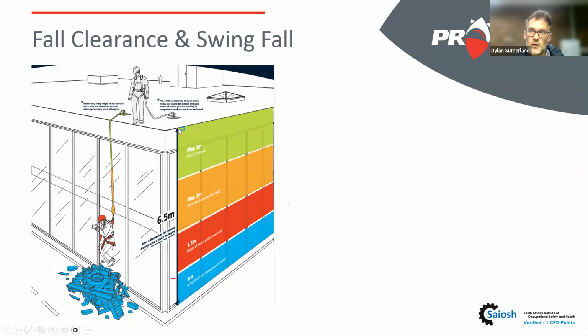In the event of that fall, if you're using a 2-meter lanyard, you'll fall the distance of the lanyard. You could fall a maximum double that length because of the shock absorber to remove the forces. What we spoke about, you had a fall factor 2, 3,400 kilograms of force. I need to remove the forces on my body below 600. The shock absorber will deploy and do that job.